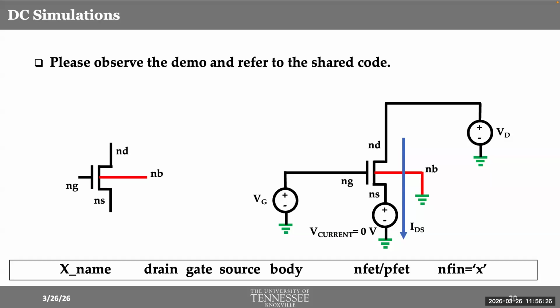Why am I connecting this voltage source? Also notice this is a 0-volt voltage source, so there is no voltage input here. So why am I connecting it? This tells you an important factor about SPICE, HSPICE. You can measure voltages at every node. It will give you the voltages for free, even if you don't need it. But it will not give you any current. You have to specifically see current through voltage sources or resistors.